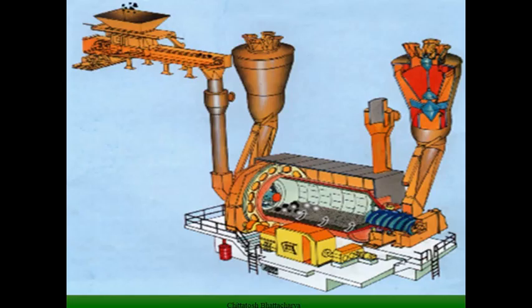Heavier coal particles are returned through a return coal chute to the coal feeding arrangement within the mill, and lighter, smaller coal particles move towards the coal carrier pipe. We have an arrangement to supply bypass air, which is part of primary air, to improve the classification, and there is a screw conveyor arrangement which rotates continuously to feed the coal into the milling system.